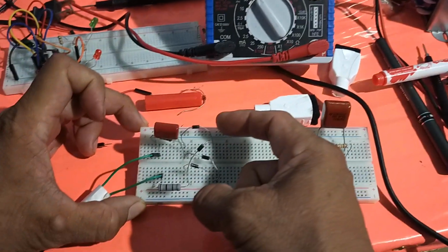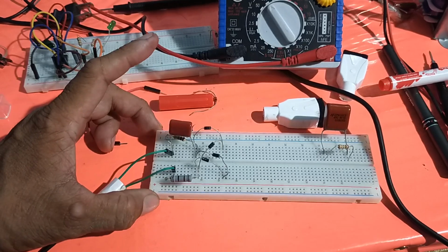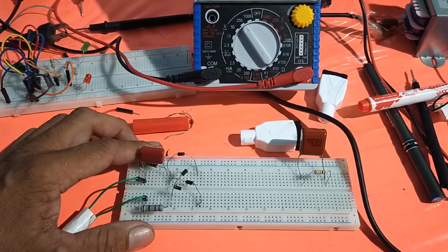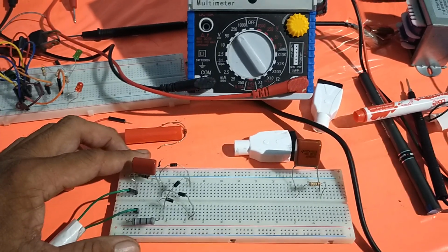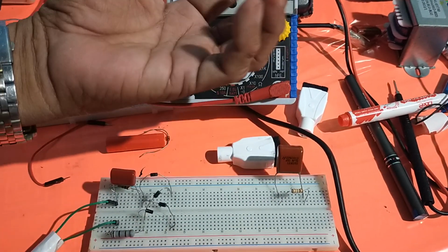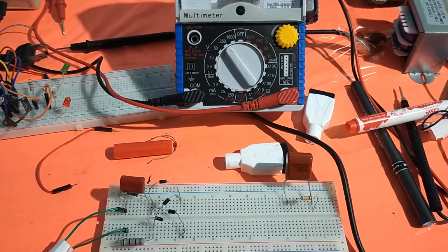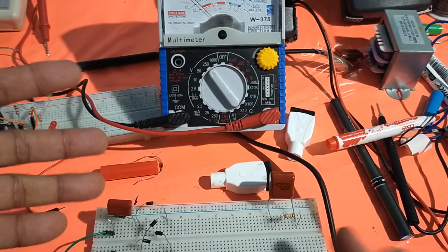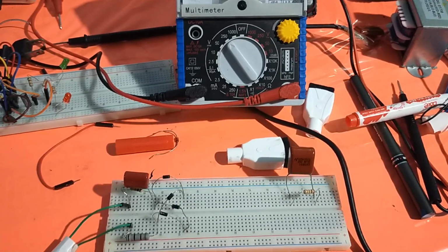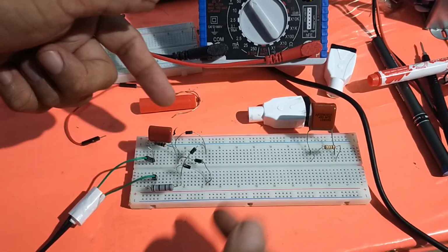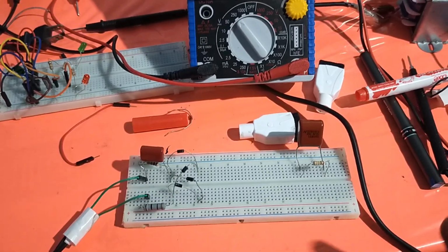By the way, what is the specification rating of these four diodes? They are actually 1N4007, wherein the peak inverse voltage is 1000 volts. The peak inverse voltage is the voltage of the diode in the reverse direction, because the forward bias voltage of these diodes is 0.7 volts. Each of these diodes will usually introduce 0.7 volts in order to operate in full swing.